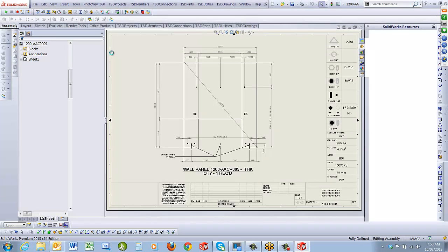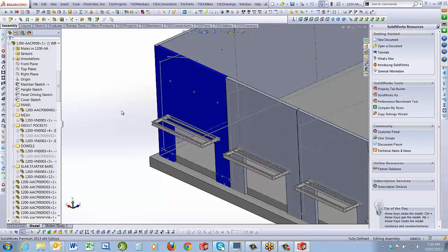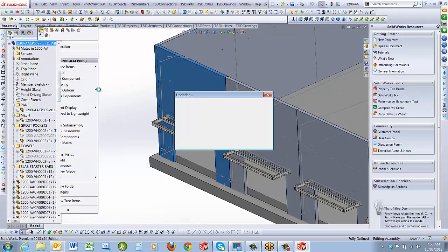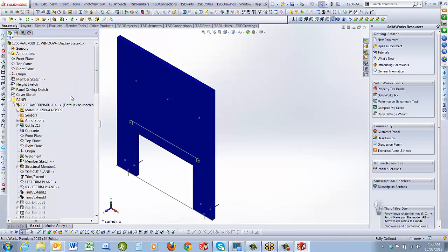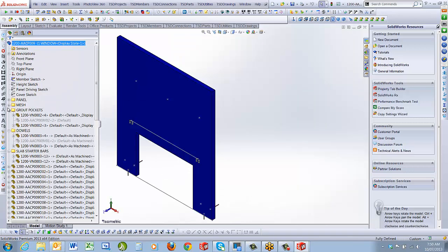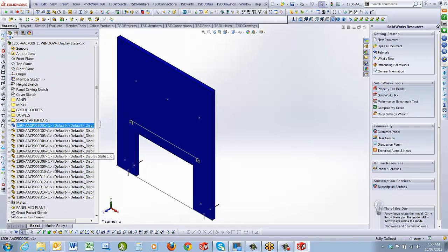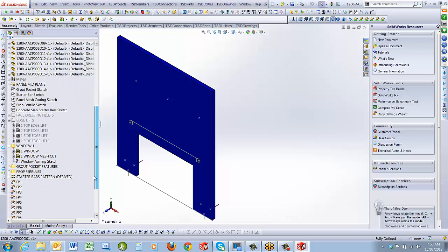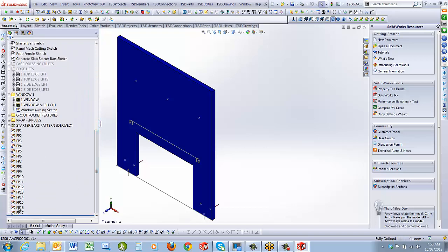And now you'll see with the drawing, we didn't go in and dimension the holes for the awning too. We probably should have. Okay. So now if I open up that panel, you'll notice now I've got all my ferrule symbols in there. Automatically pick the size to match based on that little table I showed you before. These D's right through to 15 are your ferrule symbols. Okay. And it's also created points. These are snap points, so that if you move anything after you've done the panel lock, the snap points remain.